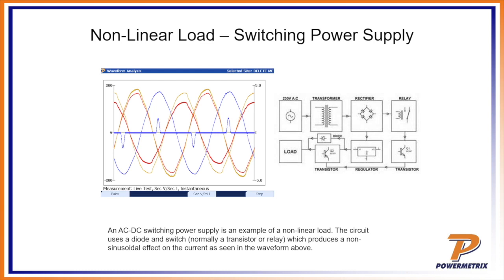If you look at an AC waveform on an oscilloscope, it's nice and sinusoidal. If you look at a DC level, it's very boring. It's just a straight line, basically. But really the rectifier is what's doing the job of turning that from an AC into a DC signal. We then put that through a regulator circuit, which flattens it out even more. But it's really that process of running it through the rectifier that causes that to become different.